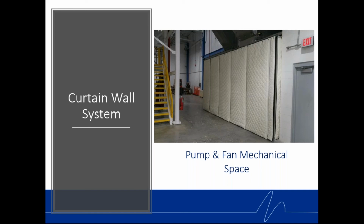So in this one, it's a curtain wall. We have a simple curtain wall here. There's actually a curtain in the background that you can't see that runs to the right, and it's making a little mechanical space. There's pumps and fans in here. And an interesting thing at this facility is you walk in this door and you go up these steps, and out of the blue, the pumps or the fan kicks on, and it kind of startles you. It's kind of unsafe, especially when you're getting on these stairs. So we make a mechanical room. This happens to be a 2 pound per square foot mass loaded vinyl sandwiched between 2 layers of quilt. So, you know, something very basic, very forgiving.